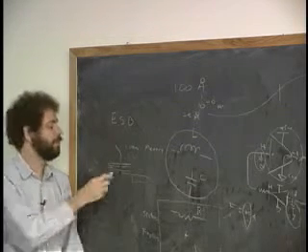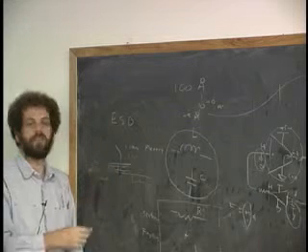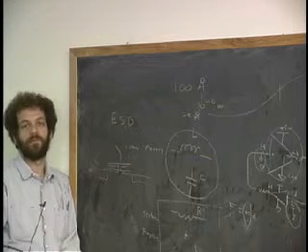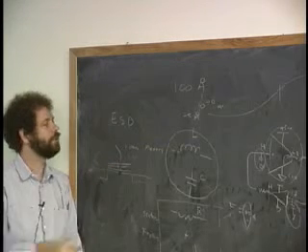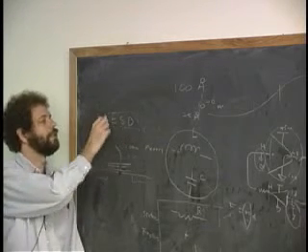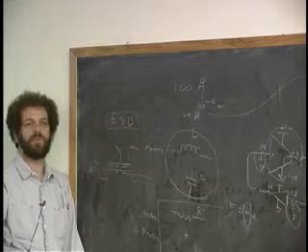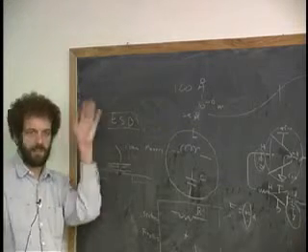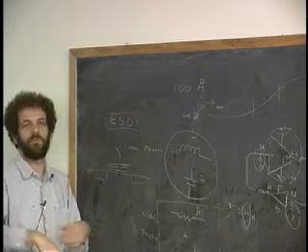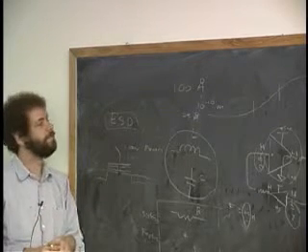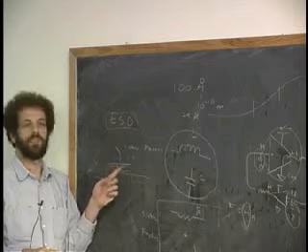And it gets to a point, and then you burn a hole in the glass, and then the chip is forever bad. So the limit to how thin you can make these things is partly issues of ESD, that you want to make sure that when somebody has a bad hair day and their hair is standing up like this and they've got lots of charge on them and they hit a key, that doesn't blow the thing up. That limits some of the sizes here.